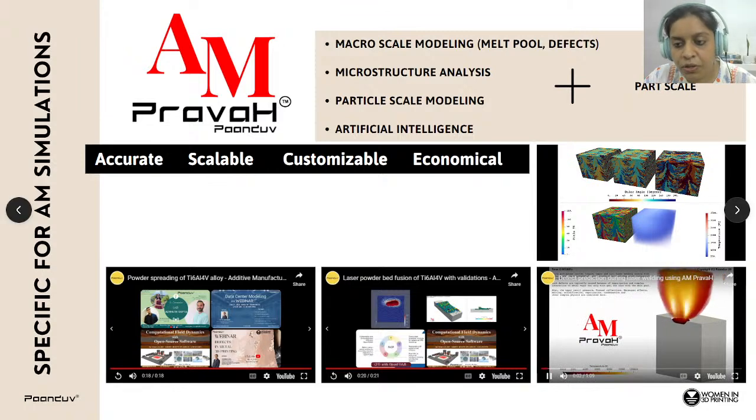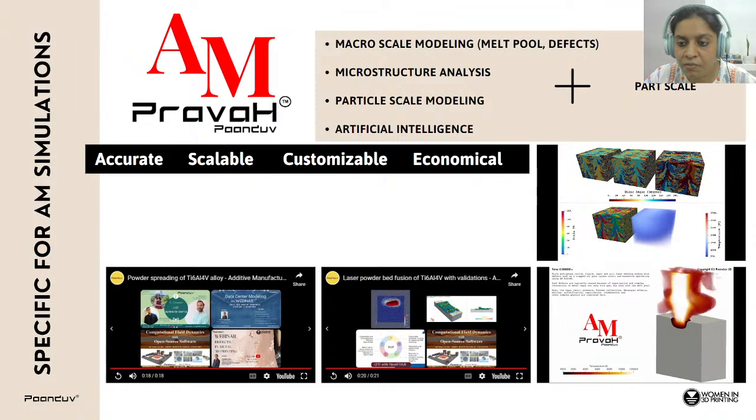Just watch this video very carefully and you will see a lot of phenomena happening here. There are 4 phases: solid, molten liquid, metal vapor, and the inert gas. The vaporization is happening and you can see how the liquid is spattering here and there. This green color is inert gas. It tries to fill in when there is nothing in the melt pool. This animation is done for a welding case, and the laser energy is high, around 1500 watts. You can see that the spattering is happening.